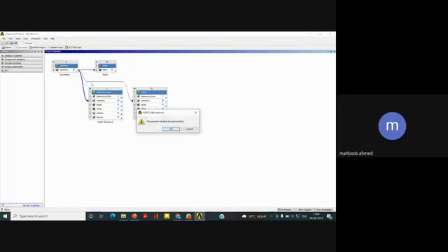I'm just deleting this. Okay, I have removed the connections. So this is engineering data, and it is showing a green tick, which means this block is up to date. Why is it so? Because we haven't provided the data yet. In ANSYS Workbench, by default, structural steel is considered as the material. Whether you select it or not, it will be selected by default.